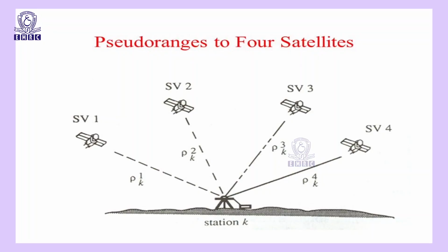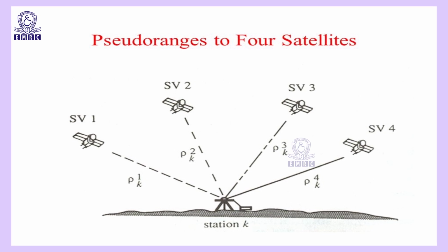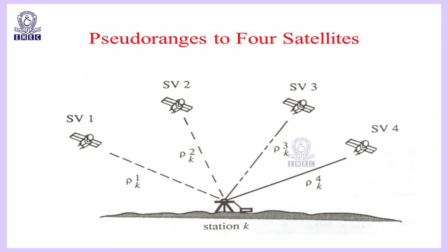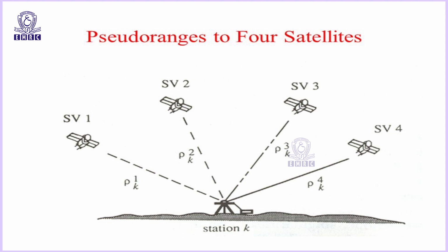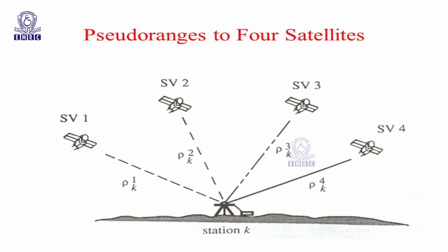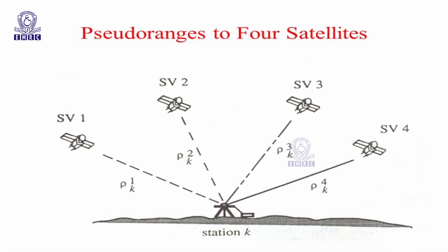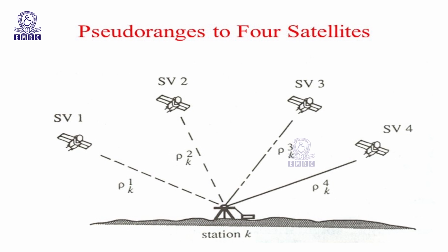The distance derived from this method of computing distance is called a pseudo range because it is not a direct measure of distance but a measurement based on time. Pseudo range is subject to several error sources including atmospheric delay and multipath errors, but also due to the initial differences between the GPS receiver and satellite time references.